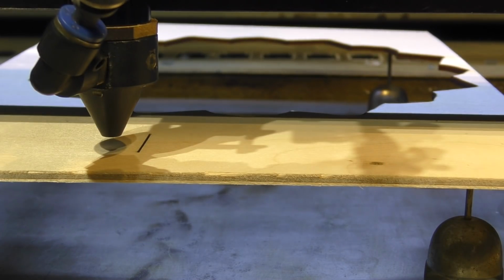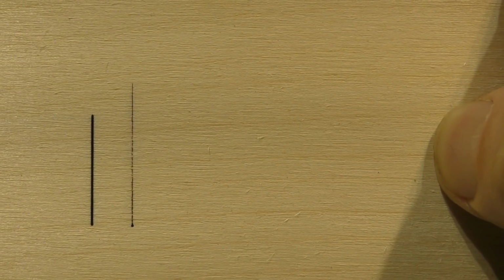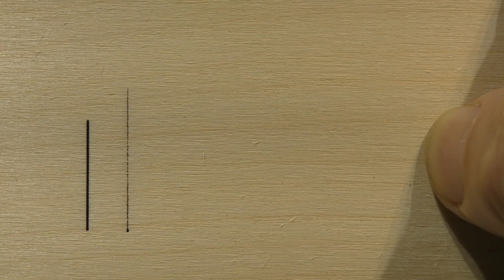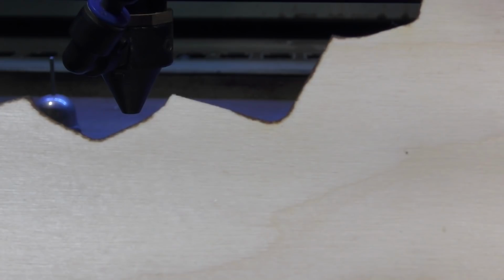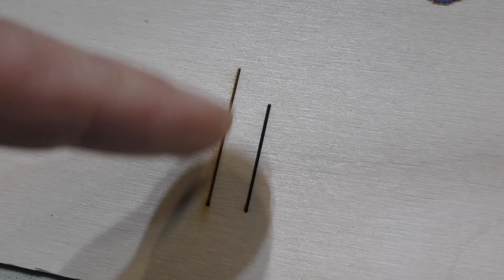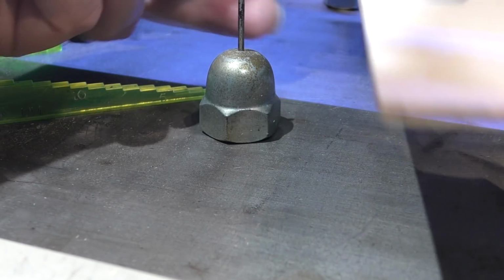So let's change to quite a fast speed now, 30mm a second. Two things you'll note. First of all, the thickness of the line is just about through. It's a just cut. But look what's happened to the surface. There is a hint on here of browning around the edge because I'm not allowing the air to pass cleanly through the cut. I'm getting some backwash from the cut itself. So I'm running too fast.